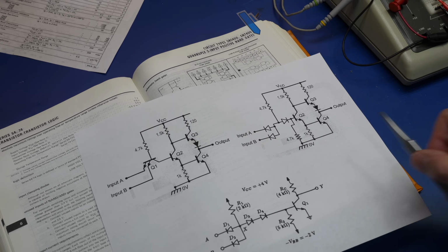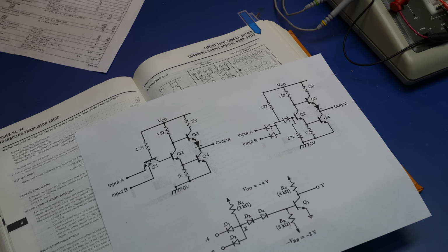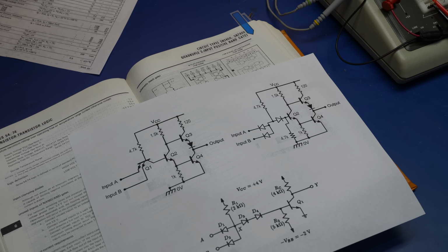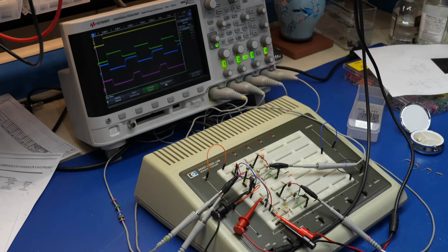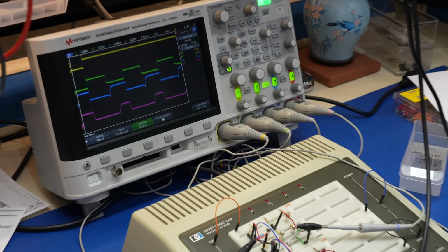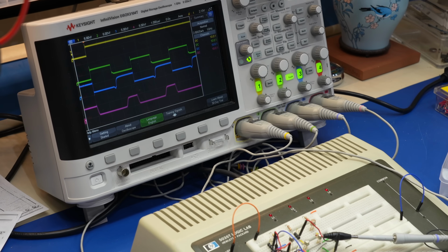So we found by poking around that there is some weird interaction with the totem pole output stage that's fixed by removing the connection between Q2 and Q4. This should already give you a clue of what's going on, but for now I'll let you stew on that. We'll come back to fix it later. The important thing is that we now have a clean Q2 output, and it makes our fundamental problems even more apparent.